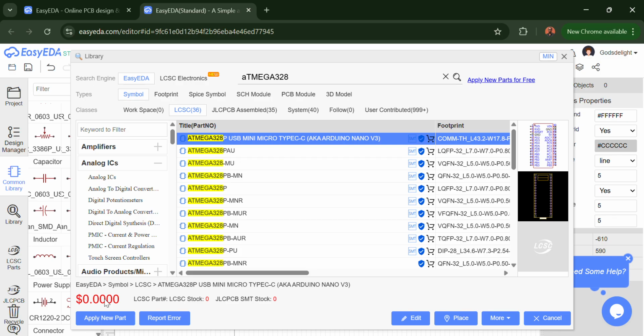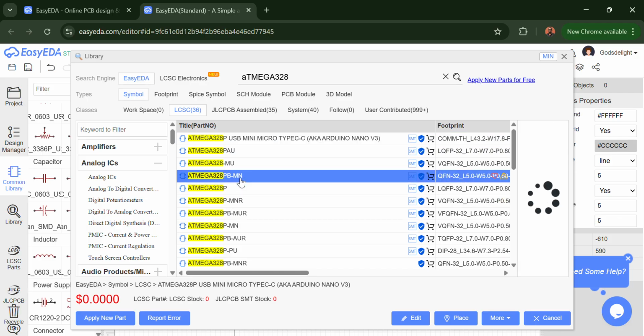The majority of that cost is going to be from the components you selected. The base board itself has a cost. Then each component being selected also has a cost. The manufacturing process has its own cost. Testing has its own cost, and so does silkscreen and other things you might want to add on top of the board. But it's very important that when you're choosing your components, you pay attention to this price. They all have their tags.